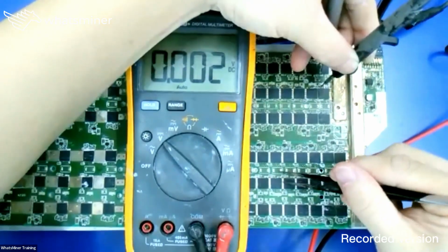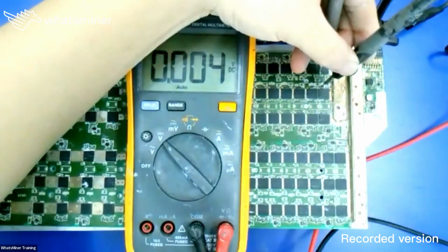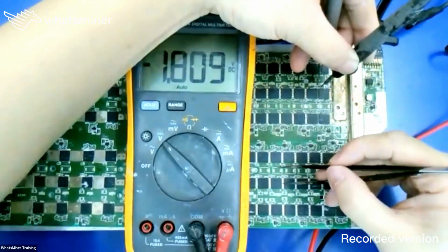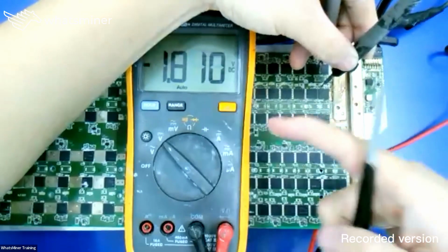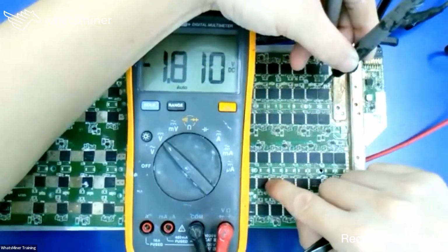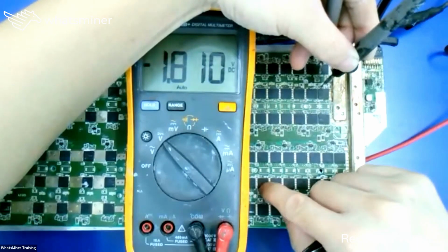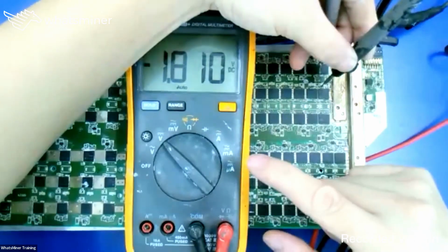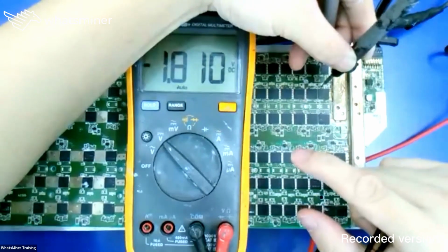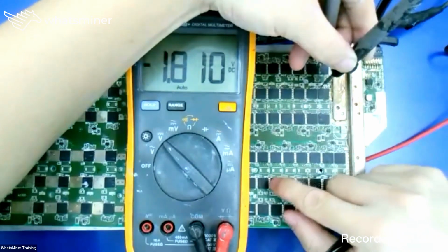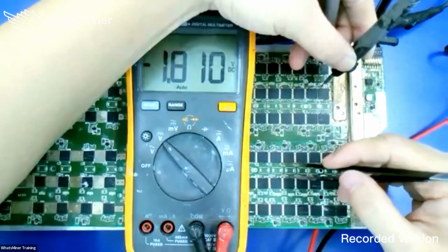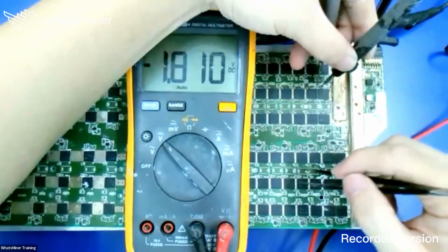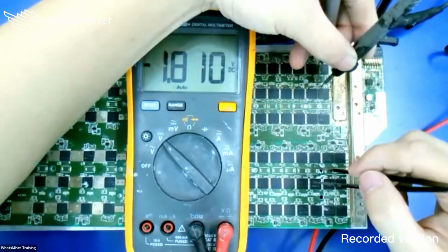For example, here, if I short it to ground and it falls to 0, that means from this chip onward, from this chip to the last chip, the whole section of the RxD is normal. So maybe the problem is just from the first chip to that chip in this section. Then you return and jump the tweezers to another chip and short.